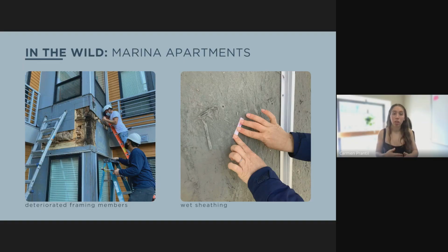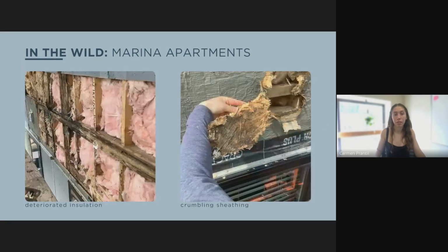But when you combine all of these, and then on top of it, you pile on that the cladding, as we mentioned before, is a flat panel, so it doesn't have that inherent shedding capability. You just have a much more elevated risk of issues. So fluid applied, OSB, no drainage plane, flat cladding. Those 4 together, each incrementally, are increasing your risk.